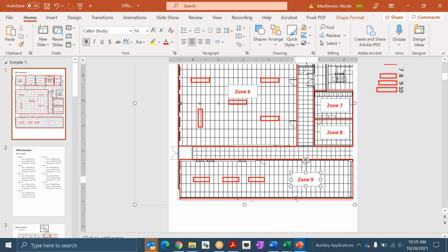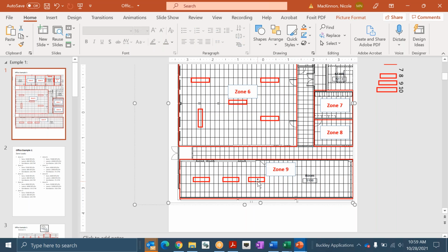So we need 5 of these. And I can already tell, but I have a lot of free space. Let's move this zone here. In some cases, if you have a data center, we get a question quite a bit about can we use chilled beams in data centers, to get some energy efficiency and treat those very dense loads. In my experience, it's actually been very difficult to make that work because chilled beams are designed to be low volume systems. Also you don't always want to have water up above the data center server racks and sensitive equipment like that, just in case you spring a leak. You won't likely have any condensation, but you could have a leaking scenario. So that's one thing we typically see people avoid.